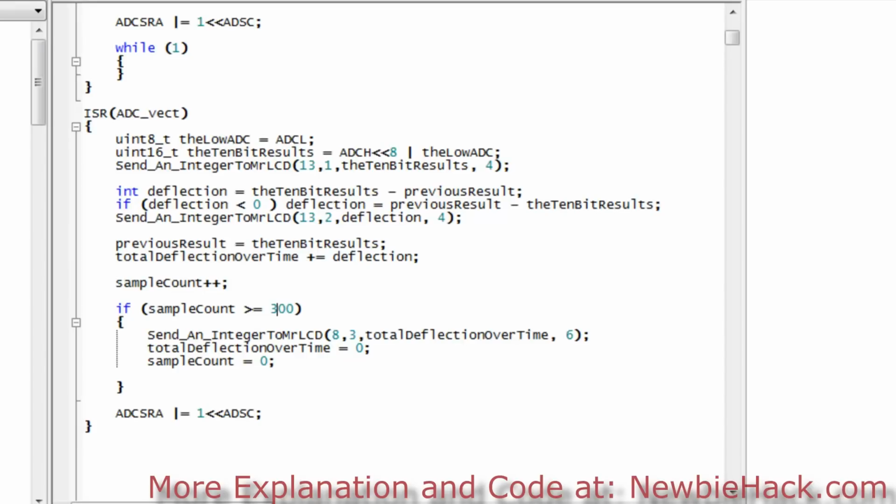And if there are other functions going on, that could also introduce noise. So there is a register that controls the sleep modes, and there's one called ADC Noise Reduction mode, and you can also use the idle mode if you wish. Both of them will work for doing conversions.